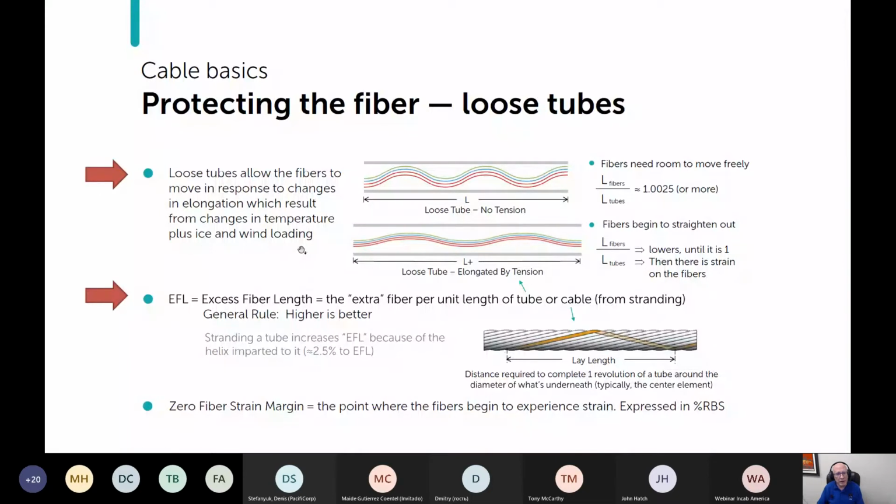And in aerial cables, and in particular with ADSS, it's not the temperature that's a problem. ADSS by its nature doesn't really change its length much in response to changes in temperature, which is a big contrast to OPGW. Metal cables change their length a lot. They have a very high thermal coefficient of expansion. ADSS and dielectric types of cable have a very low thermal coefficient of expansion. So for them, the tension is the result of wind and ice loading.